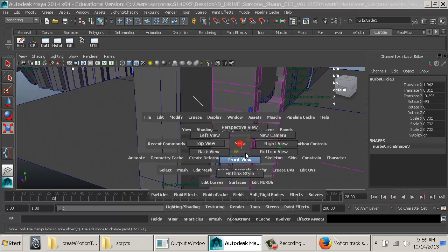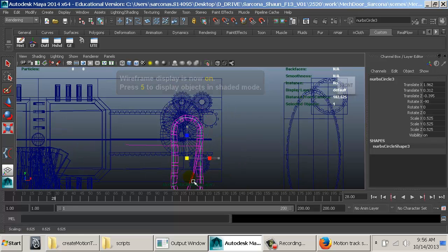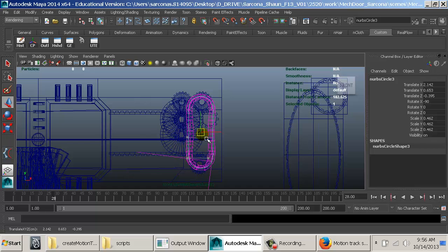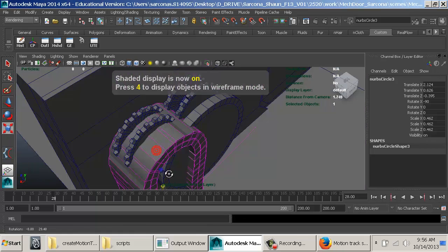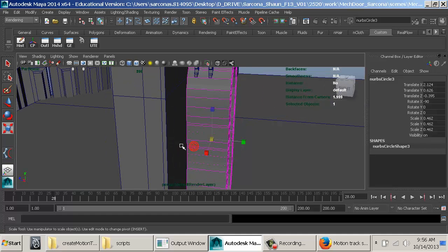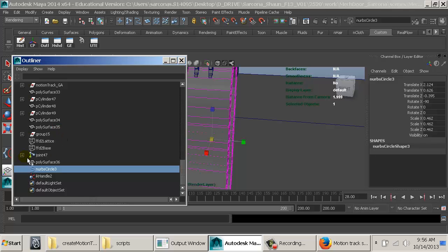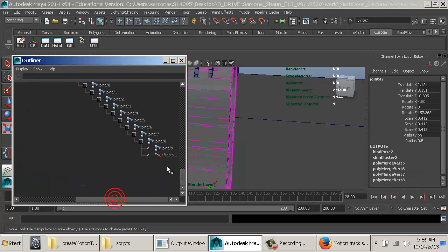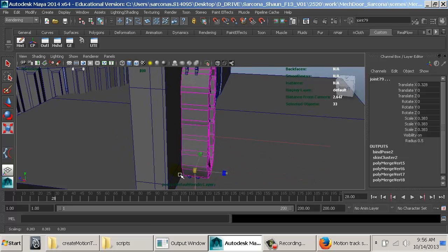And I'm going to scale the curve down because I know that the curve has to be a certain size. There's no getting around the size of that. Okay, now it's going to look funky until I get it adjusted. Okay, so let's just say it's about there. I'm going to go to my outliner, control click or shift click on my joints, the little plus sign that opens up all of them. And then I can grab them all and just scale it down until they fit.